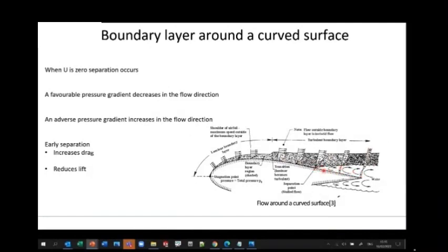So this region here is representative of our wake. Our wake is our low pressure region behind the airfoil, where our flow is actually reversed. We start to see this turbulence, this backflow in this wake, and we can see the boundary layer has actually separated from our object. Now, why is that important to us?